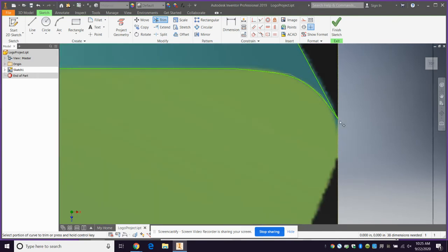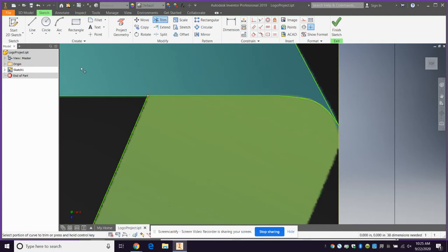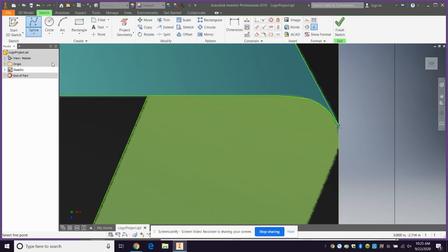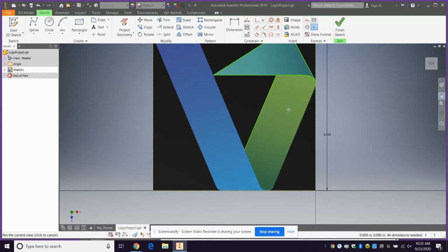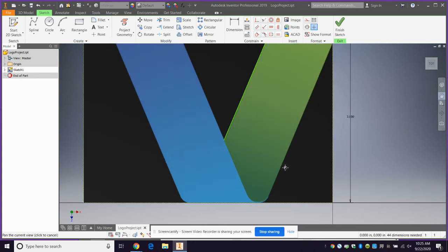Now, what's going on over here? Oh, yeah, I had some different ideas of how I wanted to do that. Well, I'm going to make a spline now. Control vertex. I'm going to connect it up there. Now, you want it to turn green like that. Then you know it's connected, right? And now I'm going to continue this spline around the corner. It's kind of going off the screen a little bit, but that's okay. All right, so I made that. You grab this little hand over here to move it around where you want it. Got a problem.